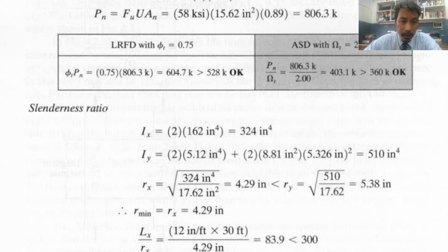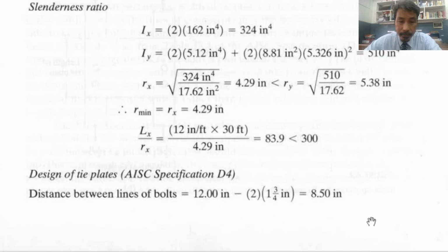Again, I already mentioned we have the concept of slenderness ratio. Slenderness ratio is dependent upon the direction axis, for the y-axis, for the x-axis, and also for the radius of gyration. So you can say that Rx, with this minimum value, you can take the slenderness ratio with respect to x. It is about this much. So we have 300.